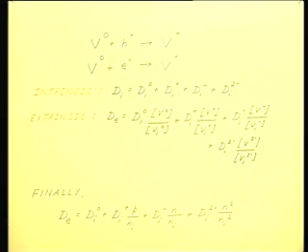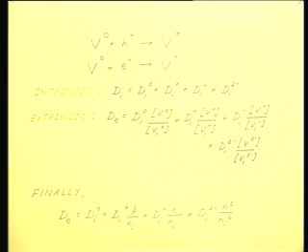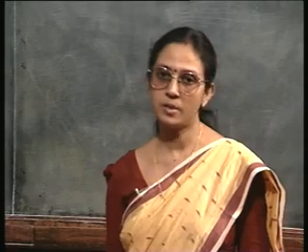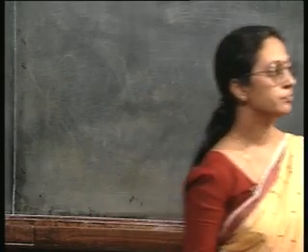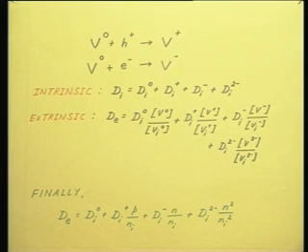Let us say, to begin with, we have vacancies which are neutral. So, V with a 0 on top means these vacancies are neutral. These neutral vacancies can act as a hole trap or as an electron trap, that is, it can accept a hole or it can accept an electron. If it accepts a hole, then it becomes a positively charged vacancy.